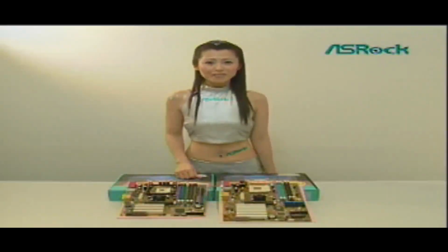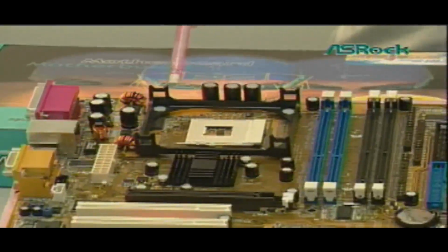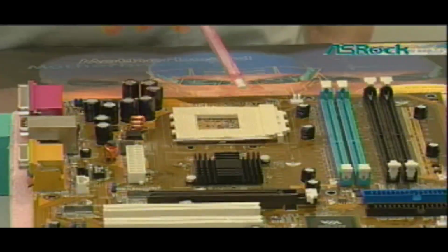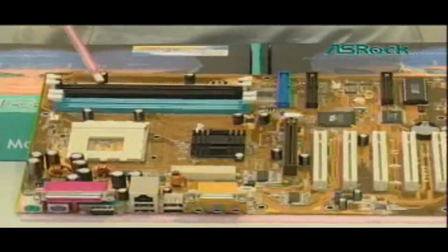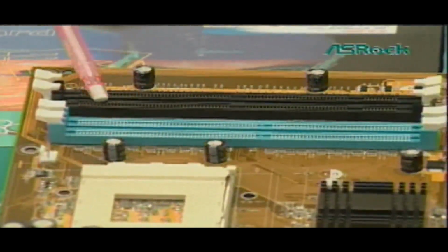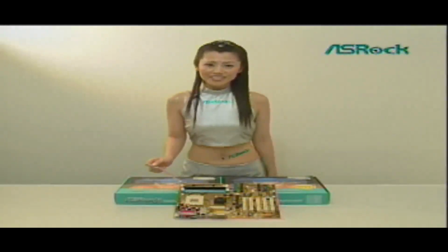There are two major CPU vendors, Intel and AMD. Socket 478 is used for Intel series CPU. Socket 462 is used for AMD K7 series CPU. As for the memory modules, there are two types of memory modules, DDR-DIMM and SDRAM-DIMM. The DDR-DIMM has 184 pins, and the SDRAM-DIMM has 168 pins. They can be easily distinguished because of the foolproof design.